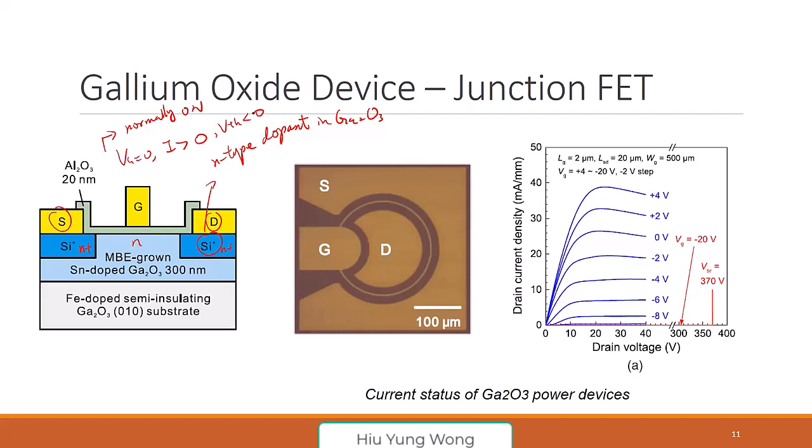So let's look at this graph. You see that this is ID-VG, ID-VD, and you see that at 0 gate voltage, it gives you current. The threshold voltage is negative, based on this about -10. Like this is a power device. You feel, wow, that is ridiculous. We are going back to the 1950s while you use -10 volts to turn off a transistor, right?